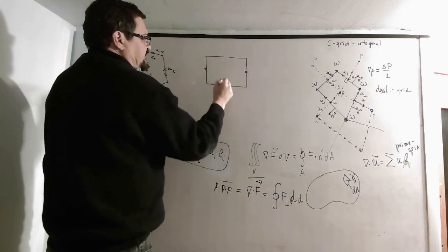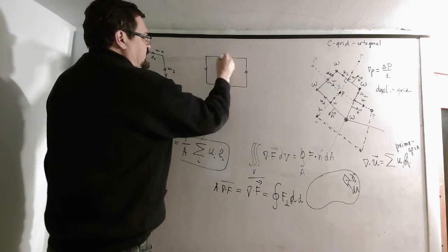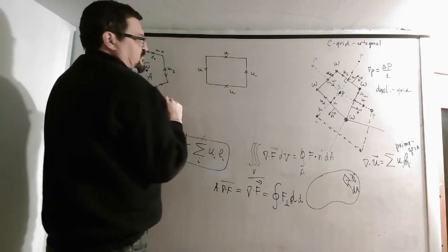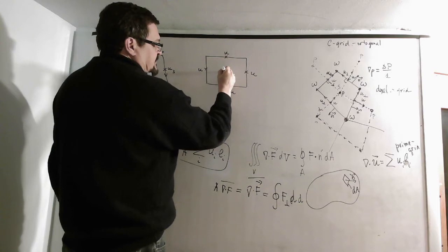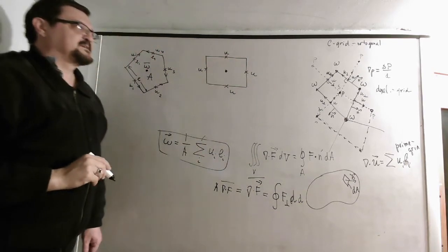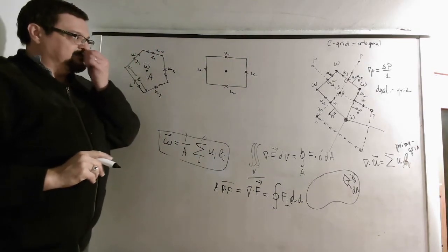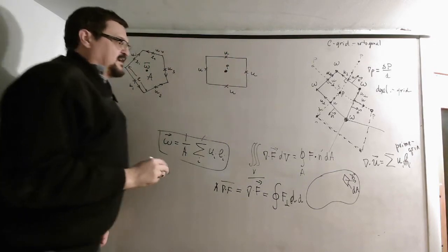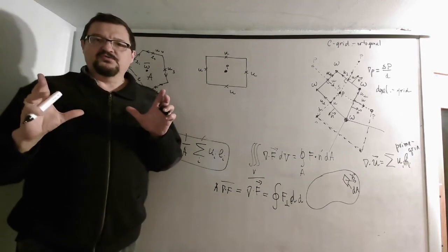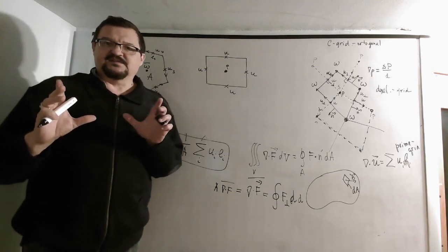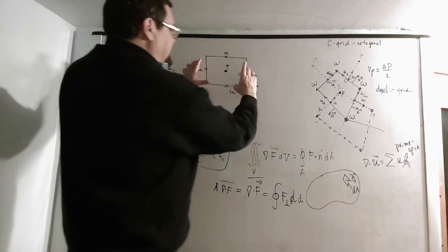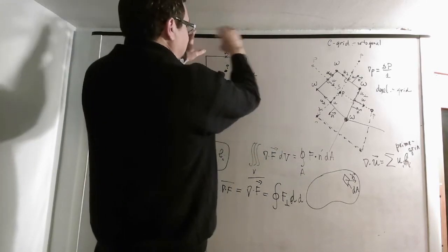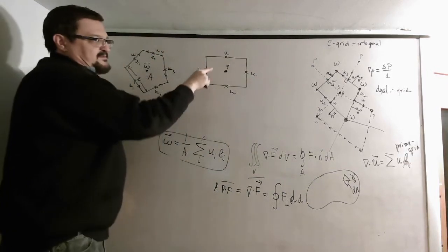So you have these points where you define your U's, your velocities, and in the center you have your scalars, or pressure, let's say. Now think about how you generate the grid. You basically have this translational symmetry. You take this element and move it to the right, and this is another grid. Then you move it north, another grid. So this is basically the basic element.